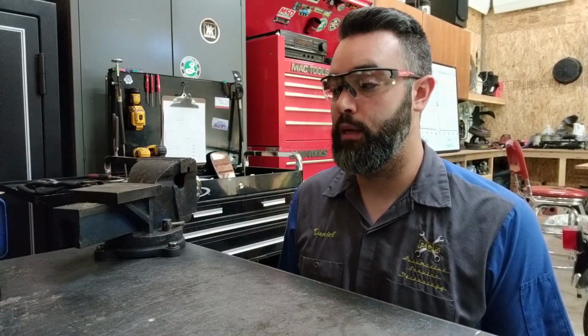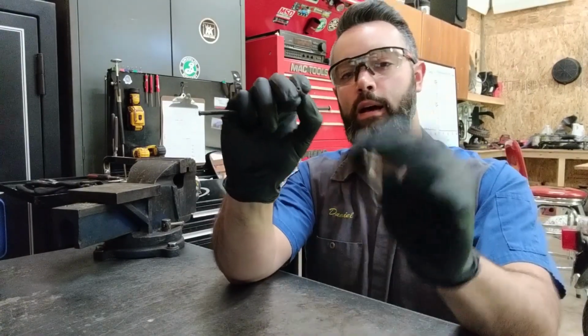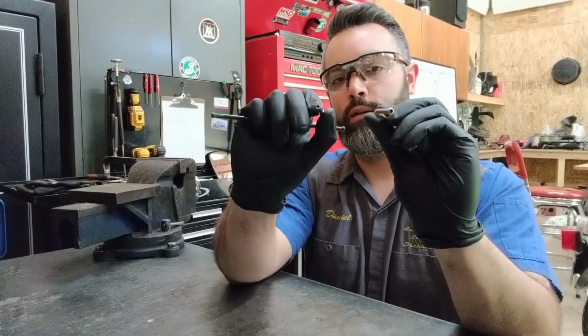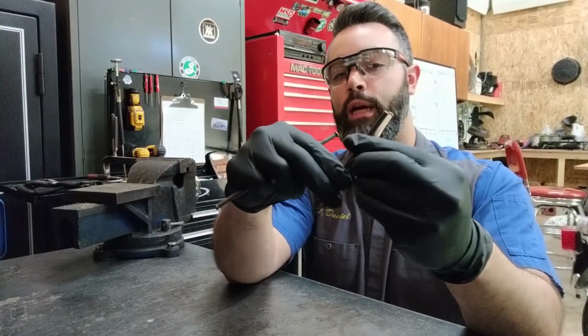In order to know the condition of a fluid, we have to do a few tests. There are multiple ways of testing moisture content in brake fluid. There is a little bit of a hang-up in that process though. Most of these fluids are water soluble, so it absorbs moisture. As moisture increases in that fluid, it will start reacting with the brake system components, with the seals, with the inside of the lines. The inside of the brake line has some copper in it.